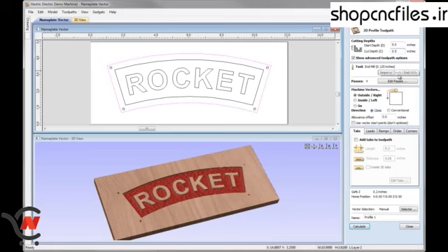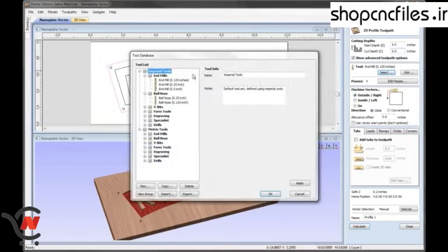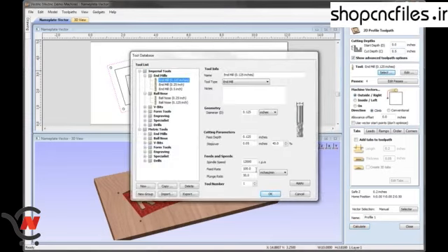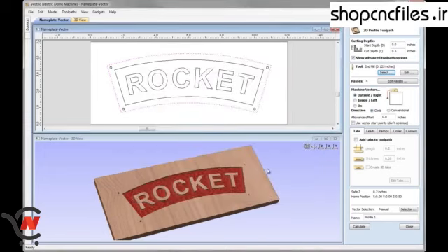0.5 of an inch. I'm going to hit select and choose the 1/8 inch end mill tool again. The main reason I'm choosing that tool is so that I don't need to change the tool between the drilling and this cutout toolpath, assuming those tools are compatible with those operations. For machining these vectors, I want to machine around the outside of them. You can see there are options to machine on the inside or on the vector itself, and in this case what I'd like to do is add tabs to the toolpath.